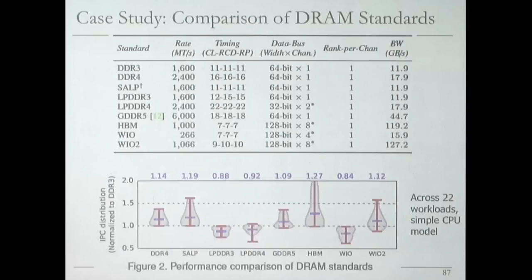That's right. So basically, this simulator, because of its flexibility and speed, enabled us to figure out that DDR4 improves performance by this much. Again, accuracy I'm not commenting on at the moment, because it's not a function of just the simulator, but also the CPU model, right? The simulator itself is modeling the memory controller as well as the DRAM itself, but it can attach to some other CPU simulator so that you can actually get performance results that look like this. It could attach to much bigger, various different CPU simulators at varying levels of fidelity. And you can read the paper for that detail.